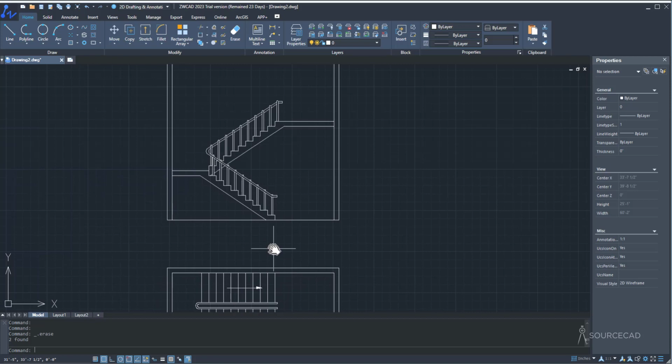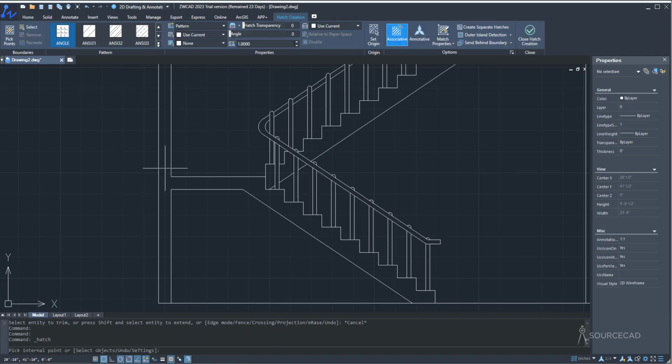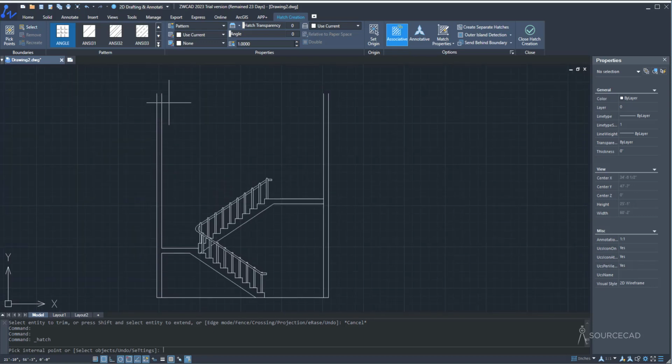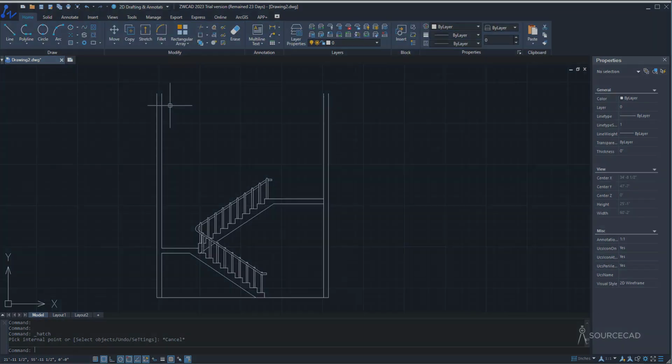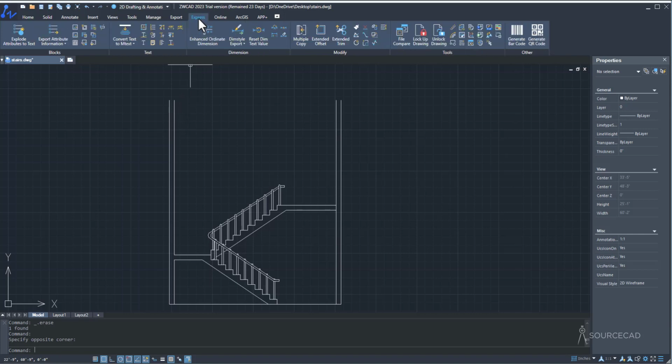So the first hatch pattern that we'll add is right here, and for that I'll actually trim this area as well. So trim, enter, trim this, and now I'll go to hatch. Now this is the hatched area. Now of course this is completely open, so this won't let you make the hatch pattern here because, well, this is open, so we need to ensure that it is closed. Alright, to fix the problem with this open area here, we'll add the break line. Now you can add break line using Express tool. So I'll go to Express, and here we have the break line symbol.